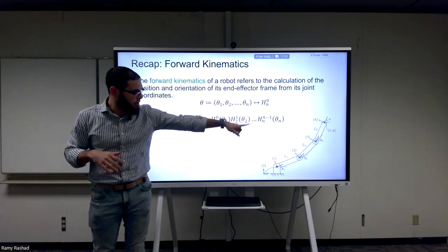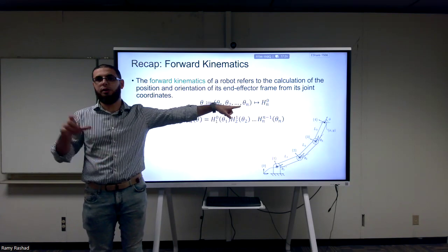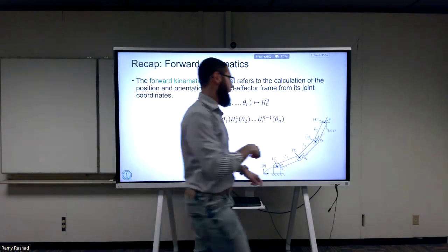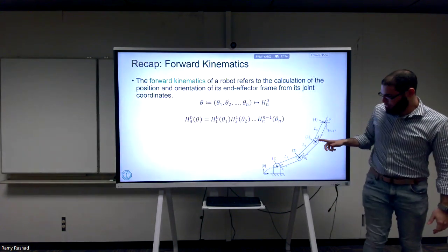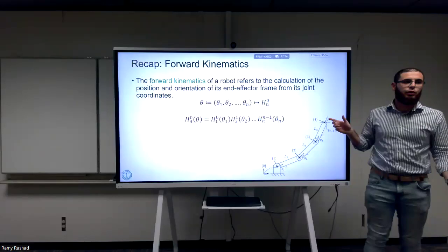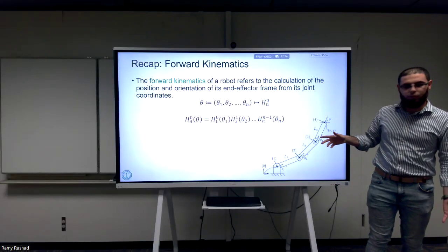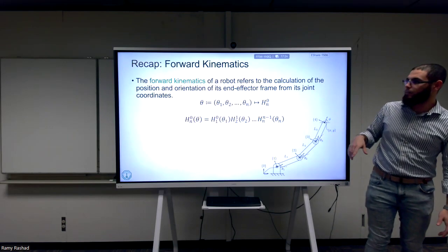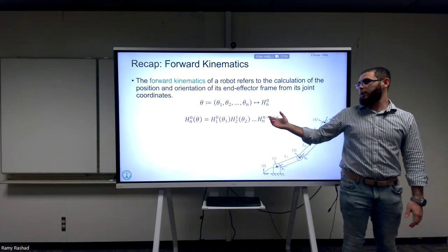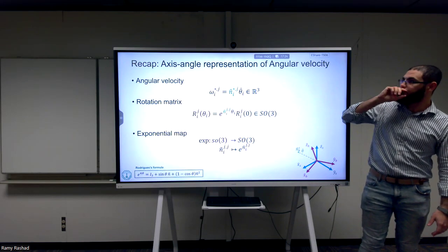We can have here, for example, a 3-link manipulator, but we have 2 joints on the 2 frames on the last link, because we're interested in having, for example, this at the 3rd joint. So this is the first joint, this is the second joint, this is the 3rd joint. While here we don't have any joints, and we just have a constant homogeneous transformation between frame 3 and frame 4. In general, we would have 1 joint connecting each of these 2 frames. So this is the general formula.